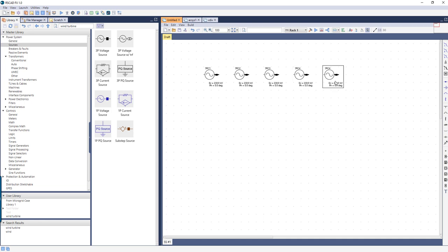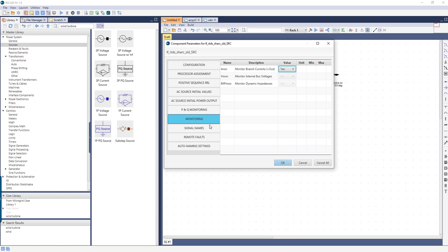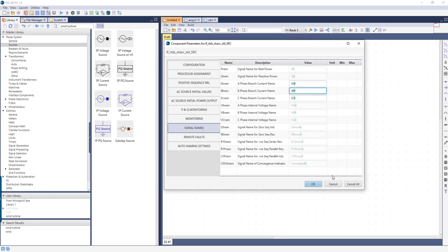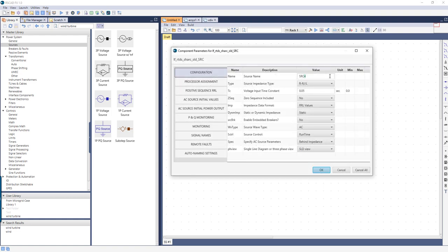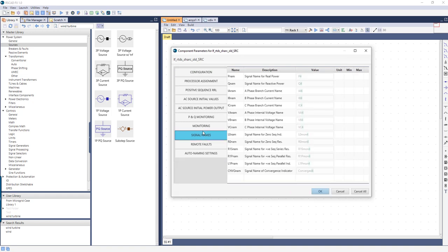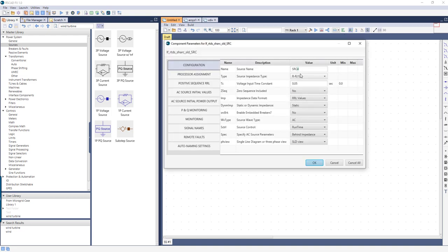So if I open up a component and take a look at most of the character fields, that is the parameters where typically you're entering a name, I can see this small highlighted portion, and that represents the enumerator. And if I open up this source component that I placed on the canvas when auto-naming incrementation was turned off, I can still see that the enumerator exists. It just wasn't incremented at the time. So you can see that when a field with the enumerator is not being edited, when I've clicked outside of the field, it shows the enumerator's current value.